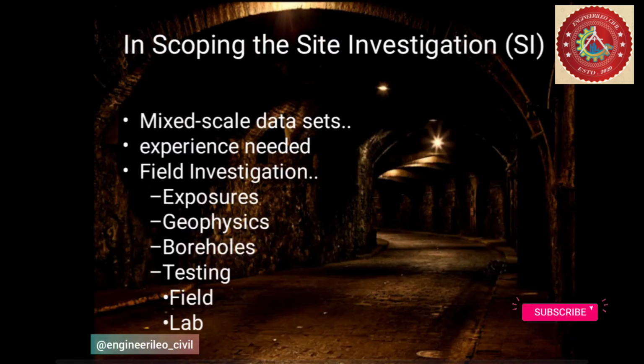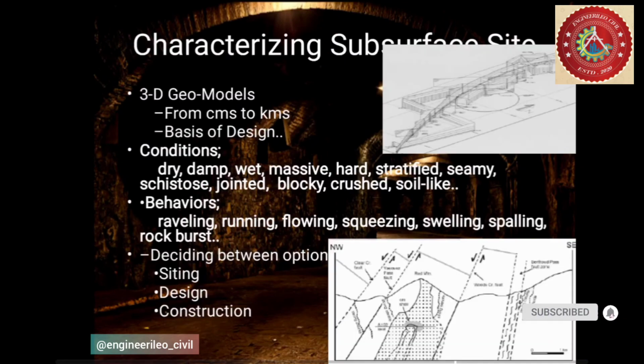Now in scoping the site investigations, mixed scale data sets are used and experience is needed. Investigations like exposure, geophysics, borehole testing, field testing, and lab testing are very important for characterization of the subsurface site. 3D models are made from centimeters to kilometers, and the basics of design are made.